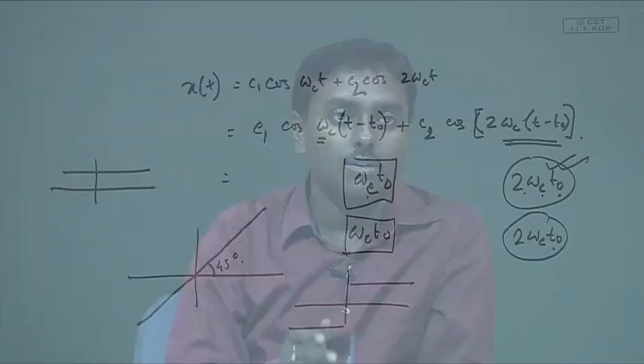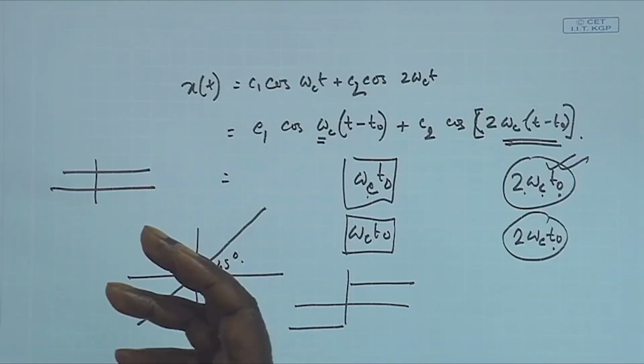Both of them, a delay element or a Hilbert transform, shift different frequencies with either different phase, or this one gives the same phase shift, and they will not touch the amplitude. But there is a certain difference, and that is why whenever you do a Hilbert transform, you will have a deformation to the signal, whereas whenever you provide a delay element, you will never see any deformation to the signal. This is the basic difference between these two.